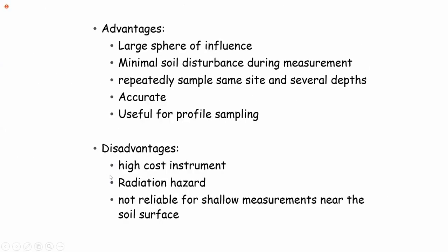But it has some disadvantages. This instrument is high cost because it has a radioactive element and also some detectors, and it has a radiation hazard. So radioactivity: during radioactivity, rays are emitted, and if you are exposed to those rays, health hazards may occur. And it is not reliable for shallow measurements near the soil surface.